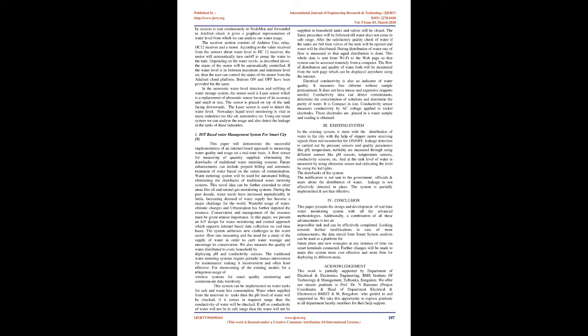The receiver section consists of an Arduino Uno, relay, HC12 receiver, and a motor. According to the value received from the sensors about the water level at the HC12 receiver, the motor will automatically turn on/off to pump the water to the tank. Depending on the water levels, as described above, the status of the motor will be automatically controlled. If the water level is between the maximum and minimum level set, then the user can control the status of the motor from the Adafruit cloud platform. Buttons for on and off have been provided for the same.